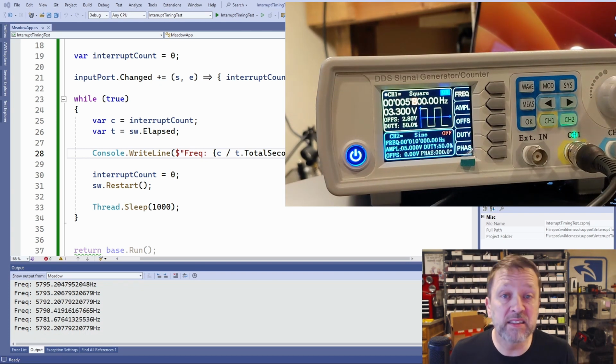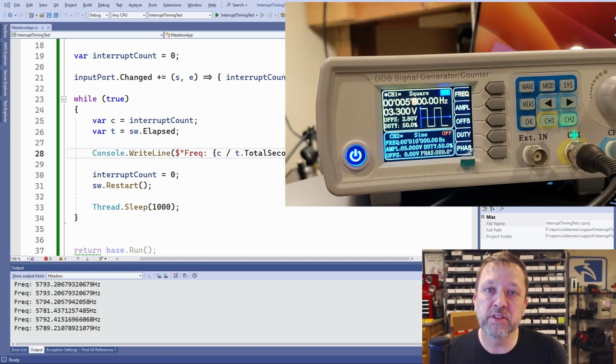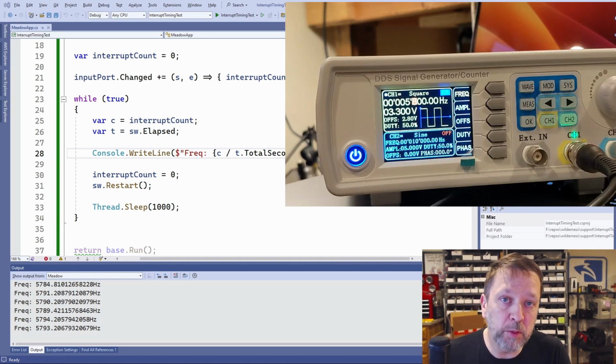You might then wonder, is this a good or is this a bad number? There really isn't a good or bad answer for that. The application itself will dictate how fast it needs to be. If I have something that is ingesting a bunch of data based on an interrupt very fast at large frequency, maybe this wouldn't be adequate. But if I just am worried about a user pushing a button, they're not going to be pushing a button near this fast.